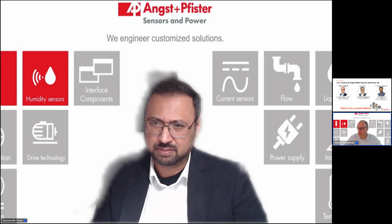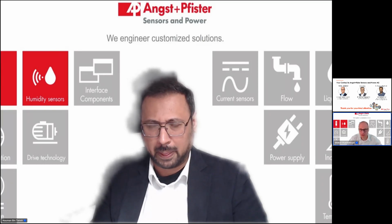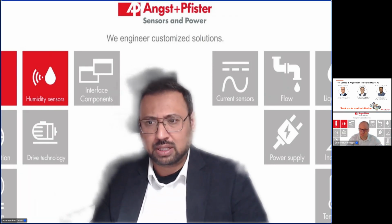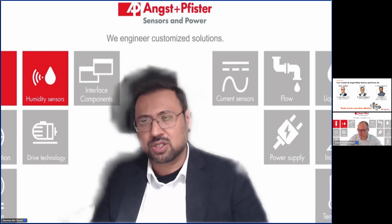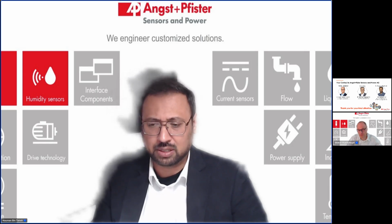Good. So one other question related to the orientation dependence. You cannot always install a sensor however you want. So is there anything to be considered when you install the sensor in terms of orientation? It depends on the technology, yes. In case of amperometric, I cannot think of any. It's the same situation, or partly the same situation, for potentiometric. However, potentiometric is definitely influenced by the orientation.